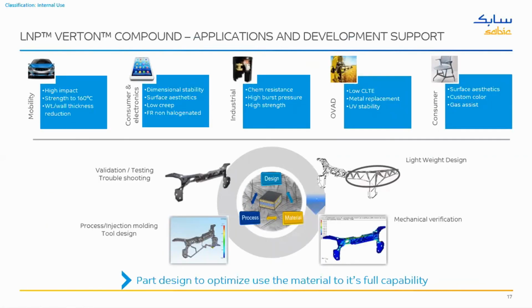And such coupled simulation is surely very important, as mentioned, for the right part design. It is very important how you can use your fibers and the fiber orientation to the best advantage of your material behavior as well as your part behavior. So how you can use them more optimally.